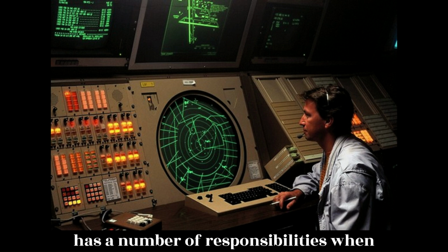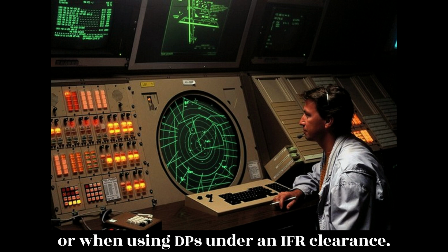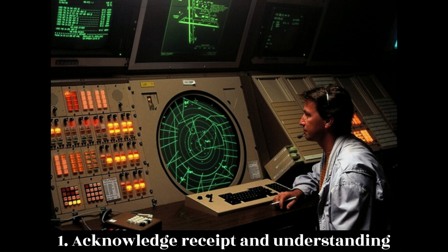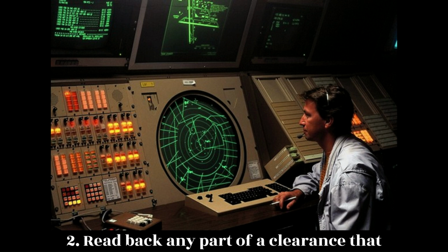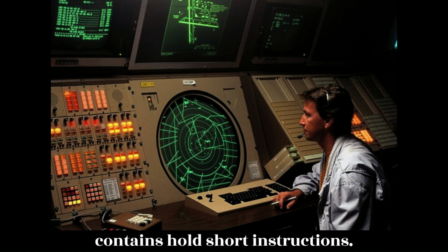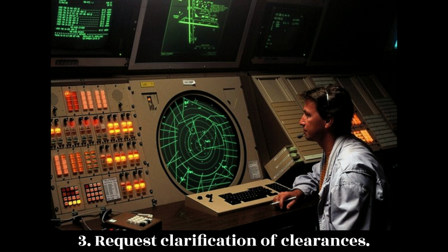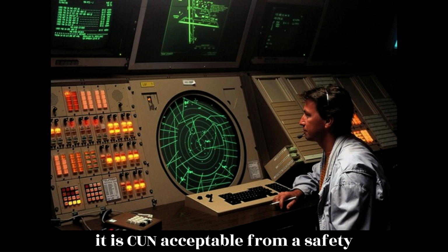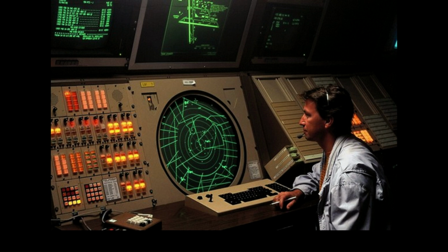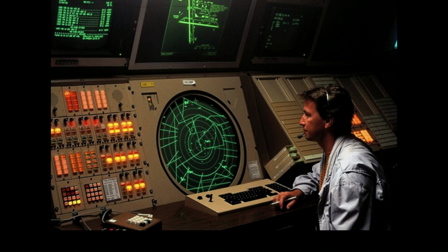The pilot has a number of responsibilities when simply operating in conjunction with ATC or when using DPs under an IFR clearance. 1. Acknowledge receipt and understanding of an ATC clearance. 2. Read back any part of a clearance that contains hold short instructions. 3. Request clarification of clearances. 4. Request an amendment to a clearance if it is unacceptable from a safety perspective. 5. Promptly comply with ATC requests. Advise ATC immediately if unable to comply with a clearance.